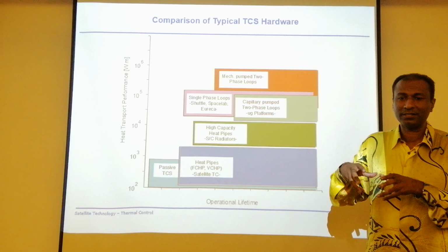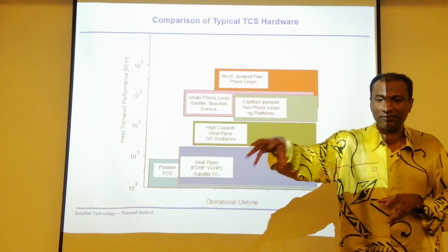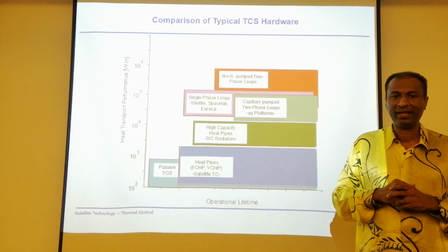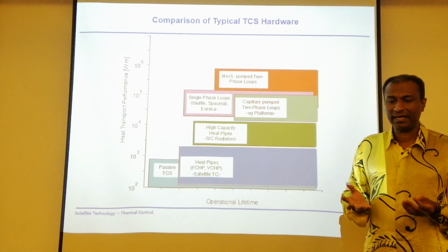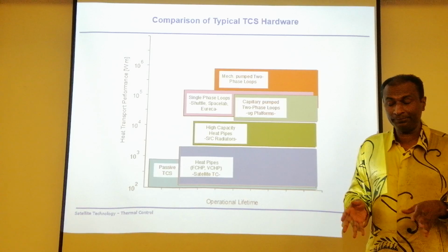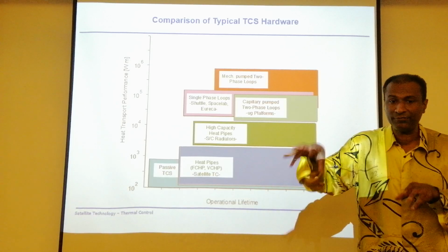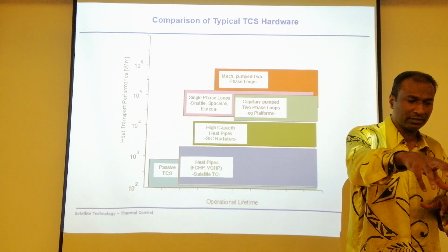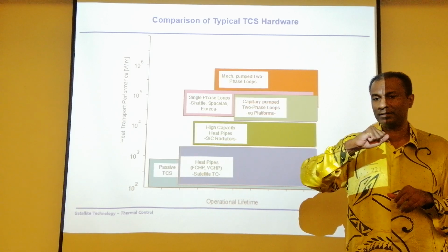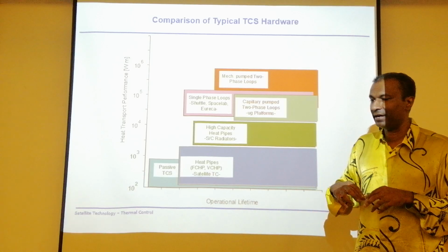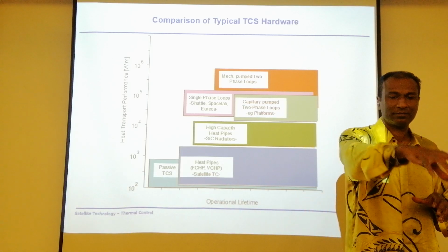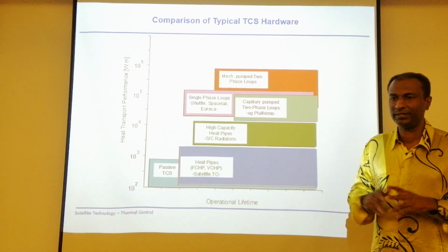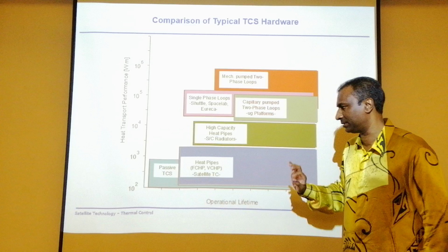Spot A, conductance is different. Spot B, conductance is different. Spot C, conductance is different. Variable conductance. You can have that depending on the actual requirement that you have. Remember, all the subsystems have different operation regions, different temperatures generated. So you can have a variable conductance heat pipe as well. It depends on the actual requirement, but these are the types that you have.